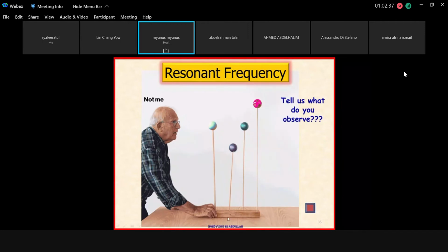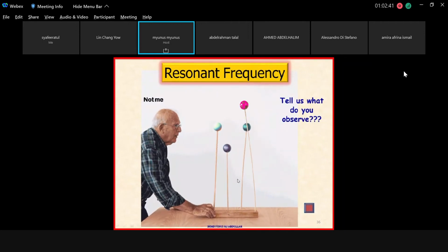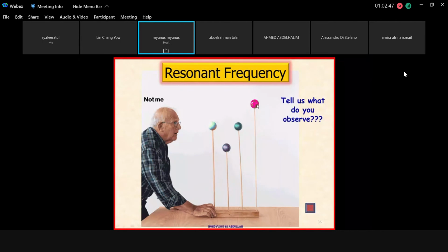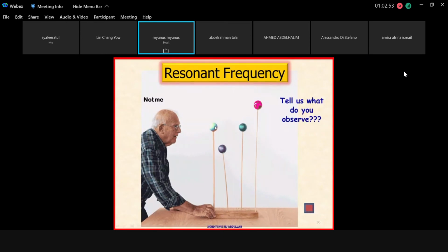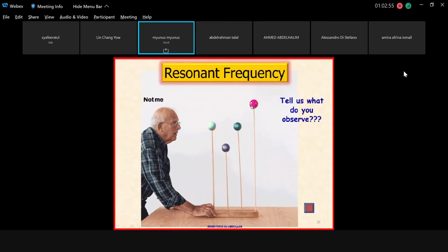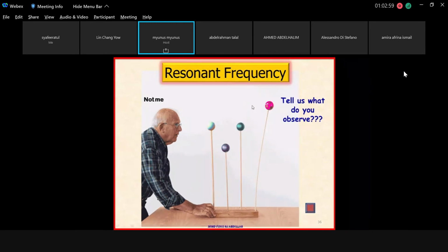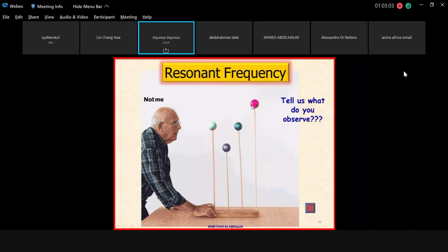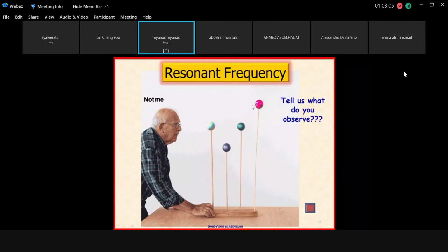So as you move, at a certain speed, only one rod will be oscillating. For example, this one is not very stiff, it is flexible, and this one is very stiff. You found that the flexible one will be vibrating much more compared to the stiffer one. That is why at the end of the day, you know that failures come when there is more deflection compared to others.